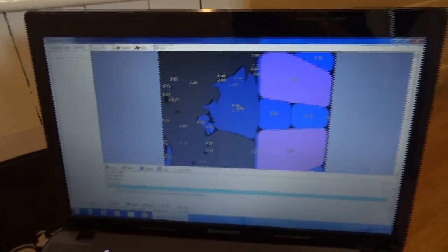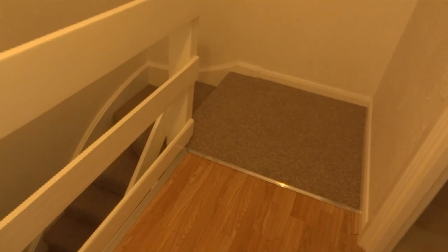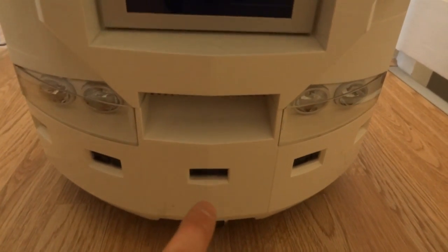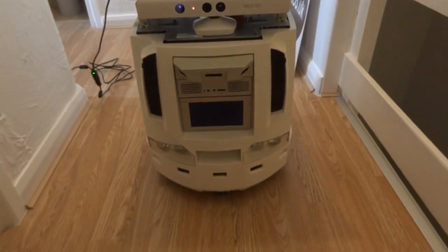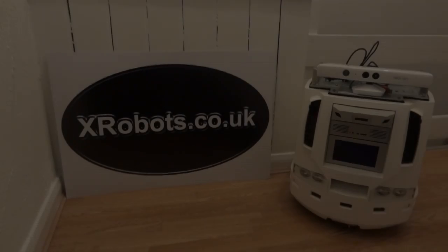So as we go around the corner here, obviously we can see the banisters in their glorious detail, and then we get pink again in the distance. We can probably just make out that doorway into the toilet, and that's all very well and good by the looks of it. Obviously the next issue is the drop for the stairs, and the Kinect isn't going to see that, but unfortunately the PC bot has these infrared sensors as well, which act as drop sensors facing down, as well as the skirt sensors, which we can use in conjunction with the Kinect data to double check what's going on. So that's all I have for this time.